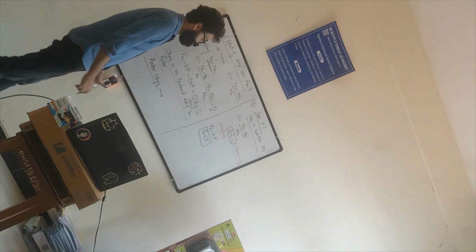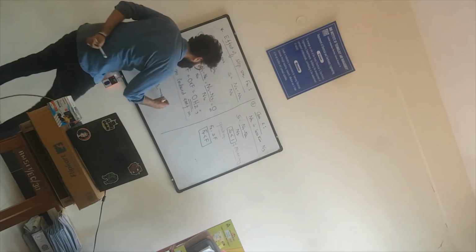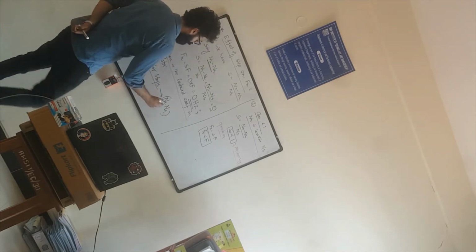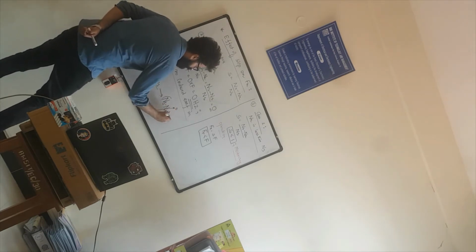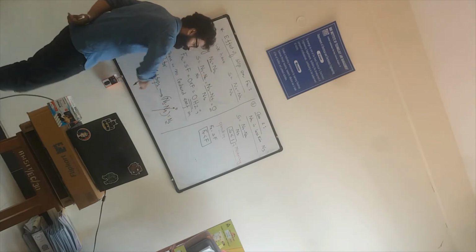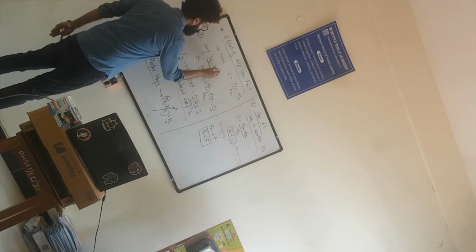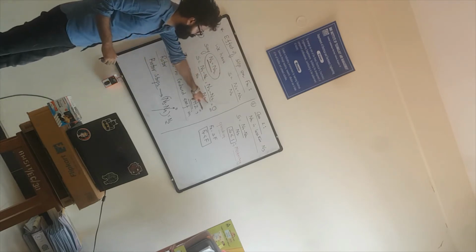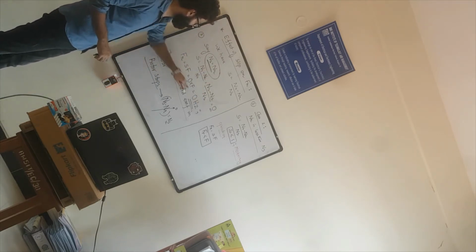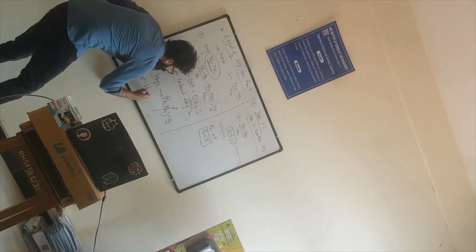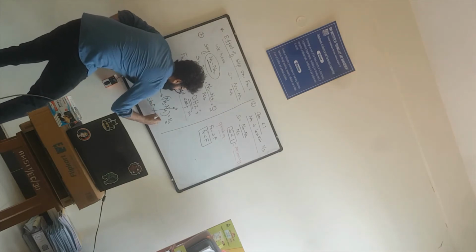Once the rotor stops, will there be any relative speed? Yes, there will be relative speed, because relative speed is Ns minus Nr. So the moment the rotor stops, Nr becomes 0, hence the relative speed becomes Ns. So once again, the motor starts rotating. And when it again touches the synchronous speed, again the slip becomes 0 and the rotor frequency becomes 0. So the motor kind of gets into start, stop, and then again it starts, and then again it stops, so on and so forth.